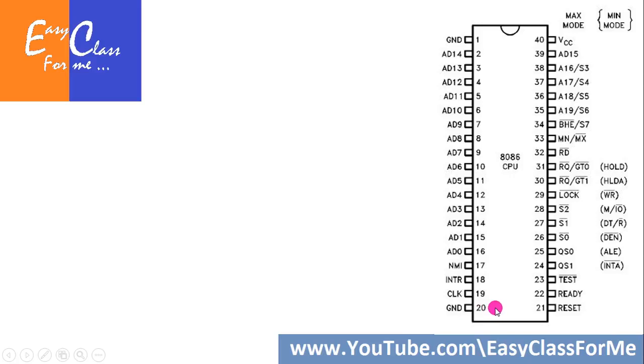Because 8086 it is having 40 pins, so it is a fairly big circuit. So since there are multiple sub circuits inside that, so to provide ground to all those circuits, while one ground is making its operation, we have 2 ground circuits here. And then now we saw that in 8086 microprocessor we had address bus of 20 bits and data bus of 16 bits. So to save the number of pins in the hardware, that is to manufacture the hardware in a cost effective manner, what they have done is they have time division multiplexed the address and data bus.